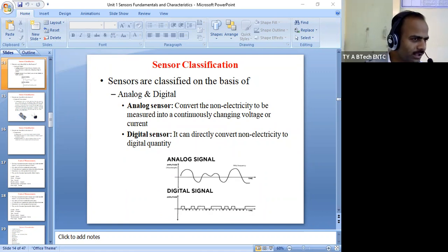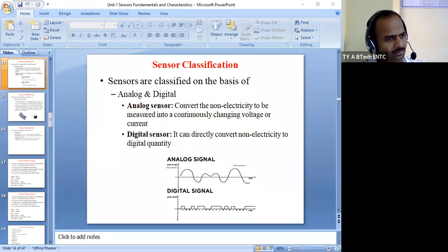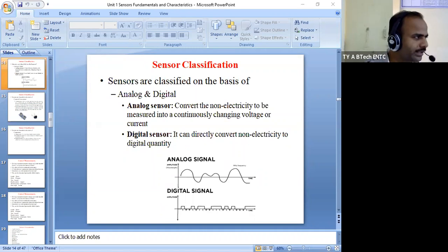Then we need to calculate the percentage of error, means the deviation divided by maximum scale multiplied by 100. 1 by 10 multiplied by 100. 10% deviation is there. Whether it is acceptable, yes or no. Next question. If your customer says no, I want only 1% deviation, error tolerance, then you have to think on this. Are you getting what I'm saying?